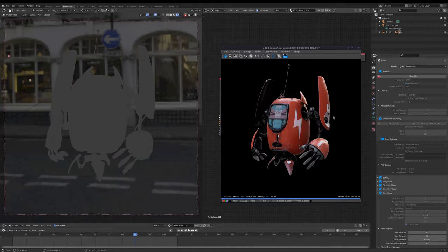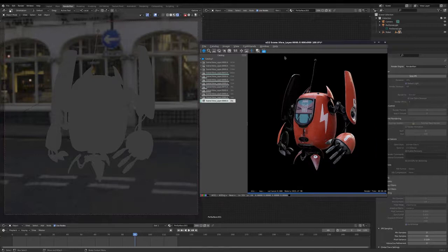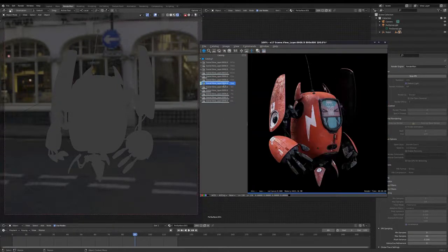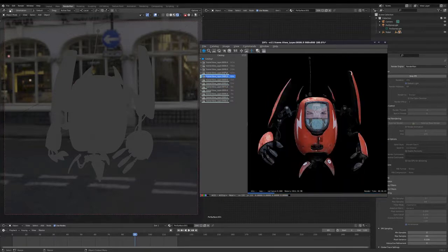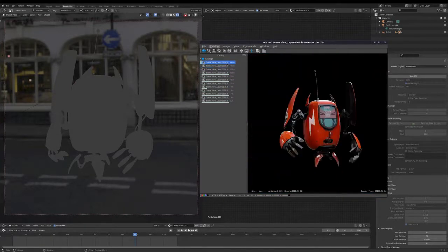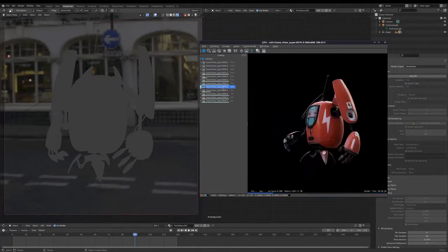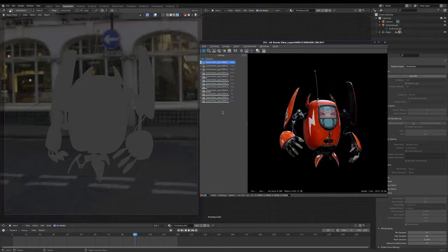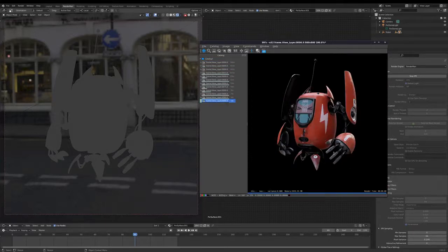But one of the things I want to show you is the catalog, and if you just press C on your keyboard, what happens is that we've now got this series of images that happens every time you start and stop either a render or an IPR. And this is really useful because now I can start to skip back through a whole bunch of renders that I was already playing around with before I started this lesson. And the nice thing about these is you can actually save all these out. So you can go export catalog, or you can go export file. And actually it's a really nice way to work because you start to document your look dev and creative process. And it has a whole bunch of other options here.